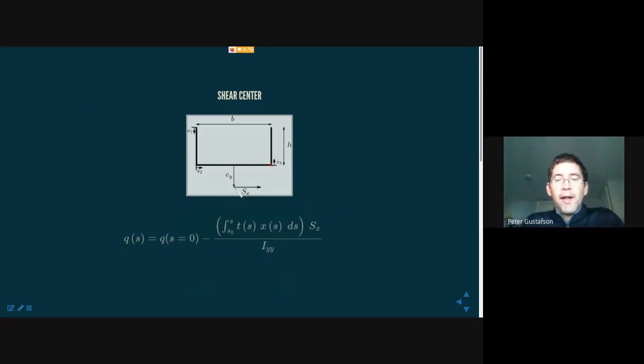For now, I'm applying a resultant load, Sx, resultant shear on the cross section, some distance, based on what we just saw with the finite element demonstration, below the channel. I'm going to call that distance EY, or eccentricity, relative to the bottom portion of the flange.